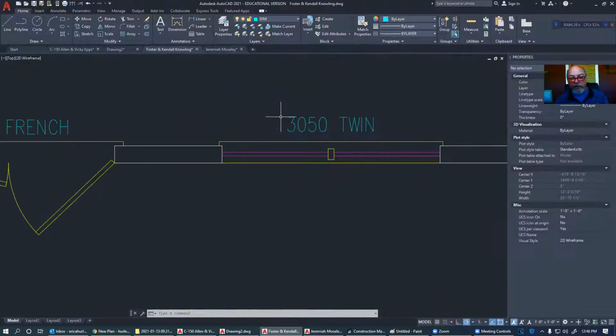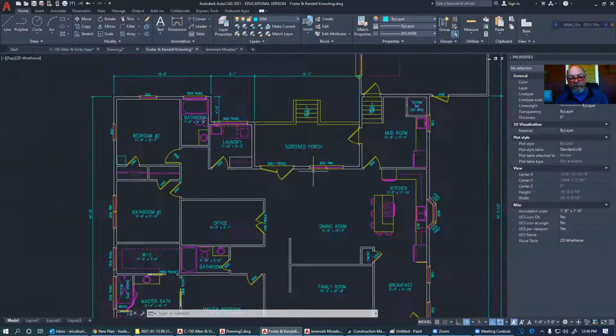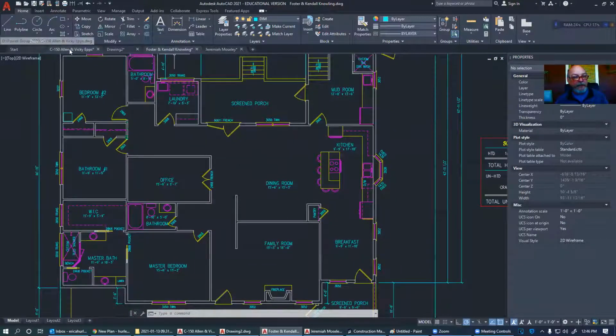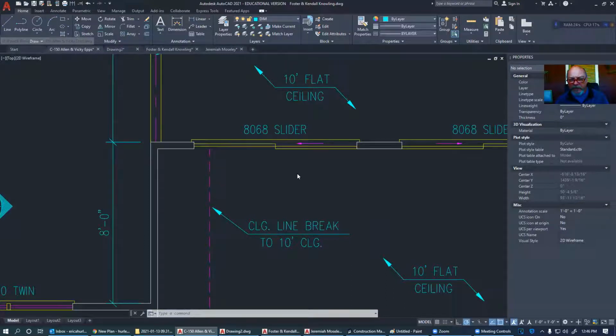And just to put it in feet and inches, if you got a window that's a twin, 3050, that's 3 foot wide. This one single window is 3 foot wide, and it's 5 foot tall, and it's a twin. And you have triples, you have quadruples, any number of things. Actually, do I have, I'm thinking I had a quadruple somewhere.